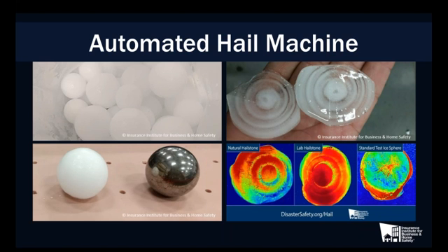So we're actually able to reproduce some of the same structures. We've actually reduced the amount of spread in the strength using our system by a factor of 2 compared to the FM injection mold method. So we're getting very good replication in the ice stones we're producing, which is vital for those impact tests.